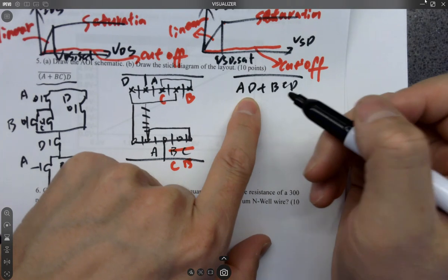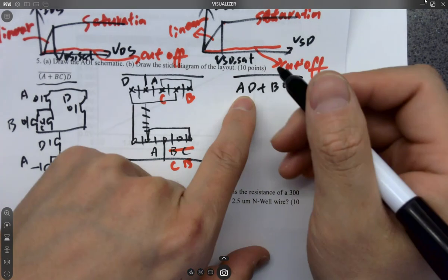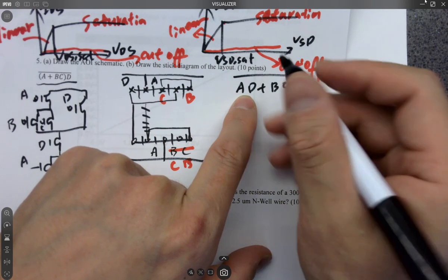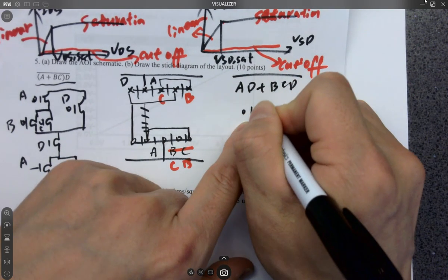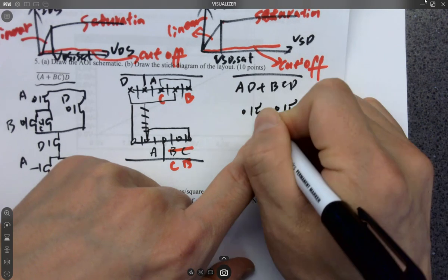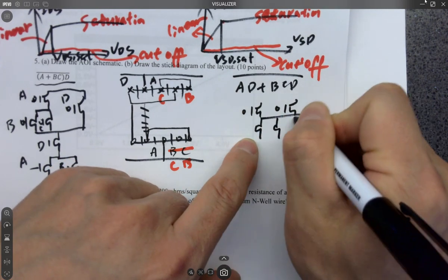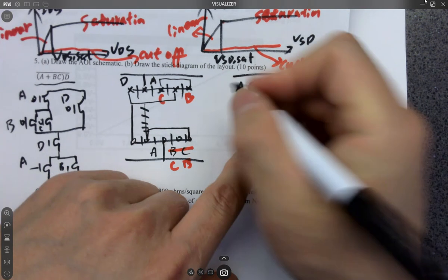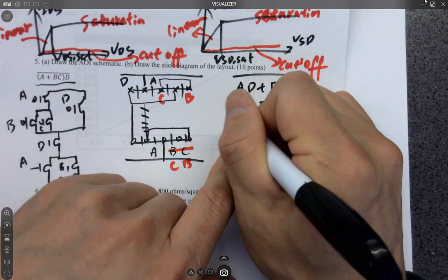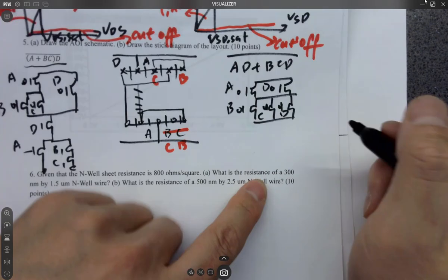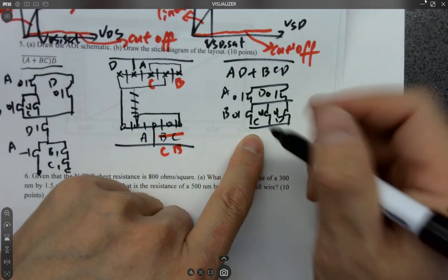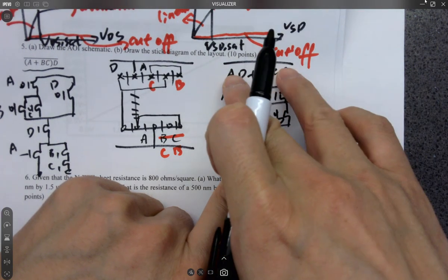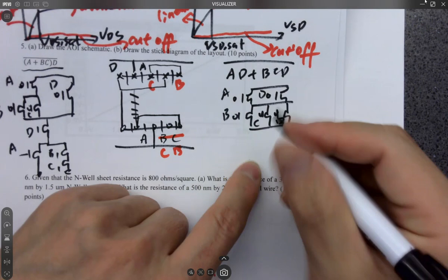Now you can see AD, think about the NAND gate structure. So the PMOSes are in parallel. So we need A and D in parallel, and B, C, D in series. AD, BCD. All right, for the bottom it will be even easier because it's just the NAND gates, two branches in parallel, right?